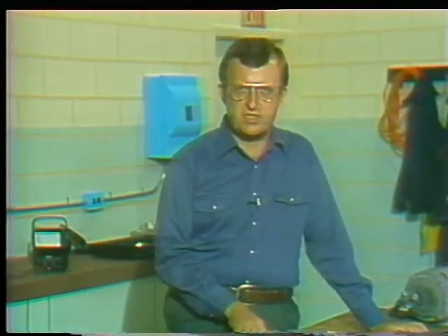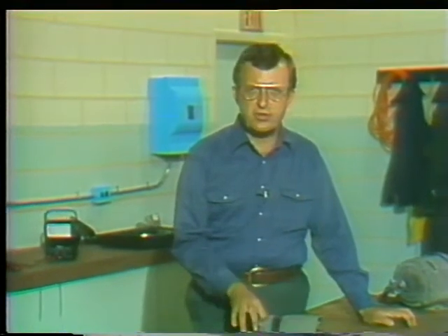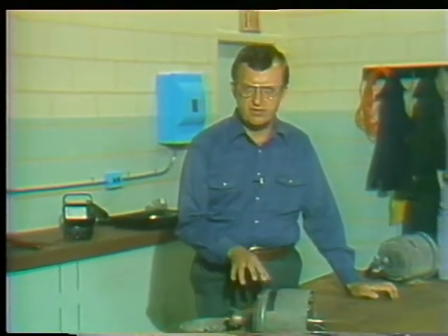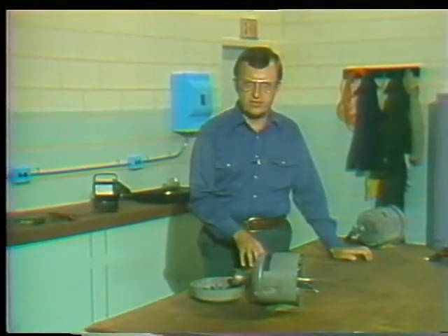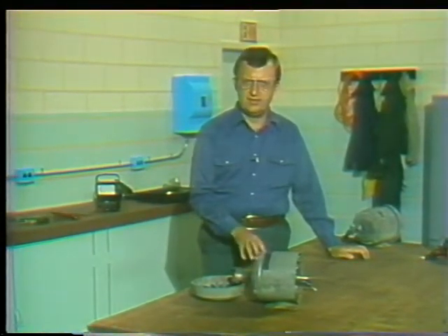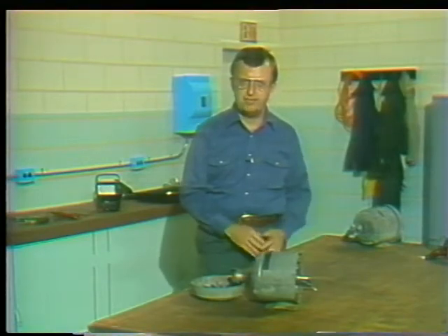Now, you can try to locate the short by testing for resistance balance in the current paths, but chances are you won't be able to find it because the imbalance may be so small that you won't see it on your meter. But if you're sure there's a problem in the stator and you've eliminated ground and opens, you can usually assume that the problem is a short. Then, in most cases, the motor has to be sent out to be rewound.